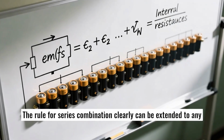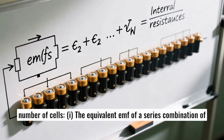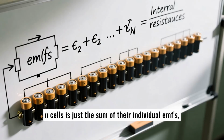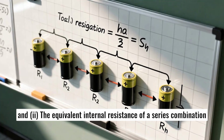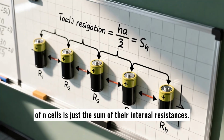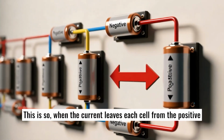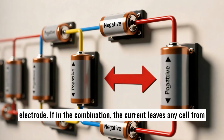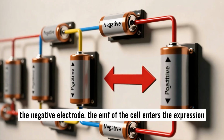The rule for series combination clearly can be extended to any number of cells. 1. The equivalent EMF of a series combination of n cells is just the sum of their individual EMFs. And 2. The equivalent internal resistance of a series combination of n cells is just the sum of their internal resistances. This is so when the current leaves each cell from the positive electrode. If in the combination, the current leaves any cell from the negative electrode, the EMF of the cell enters the expression with a negative sign.